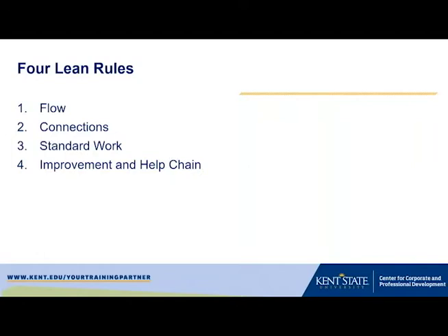You should have flow. What we mean by that is the product or service should flow, if you want to call it like a river, to the customer at their request. There's different ways to flow. The most ideal condition is one piece at a time on demand. The next best would be first in, first out in some size of a batch. The third best is supermarket style.